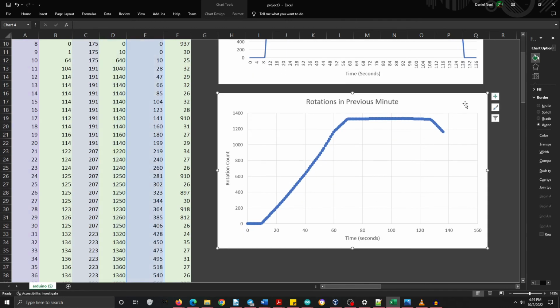And the bottom figure shows the per minute tallied RPM over time. There's an expected rise from around 10 to 70 seconds as the program backfills the 0 array, but once the fan has been running for 60 straight seconds, it maintains a fairly consistent RPM of 1320 to 1330. As mentioned, the results are stable because we tailored the demo to be a 1-minute loop.